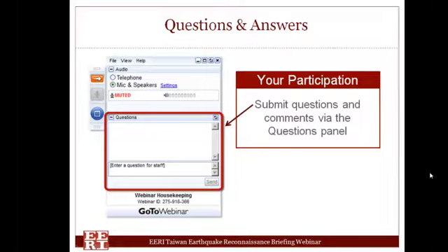Thank you both. We have probably time for one more question here as well. It's a question to both of you about liquefaction and your comment that previous earthquakes hadn't densified the soils, and the person is asking whether or not you were able to define and evaluate the critical void ratio of the liquefiable soils, that led you to the conclusion that previous earthquakes hadn't densified the soils so that liquefaction was prevented?